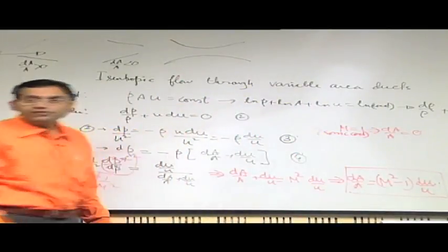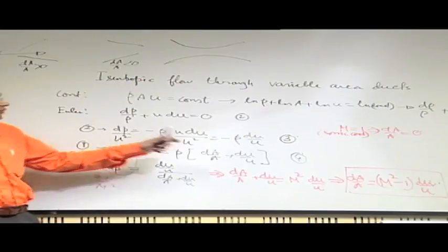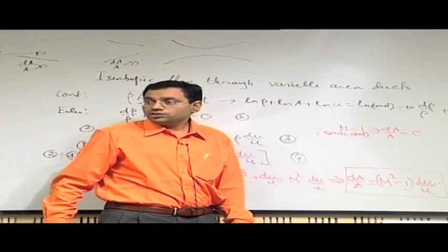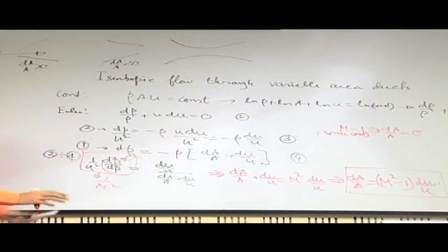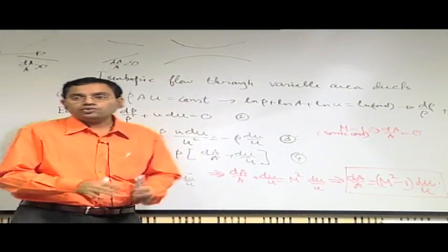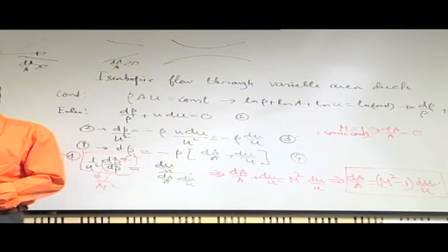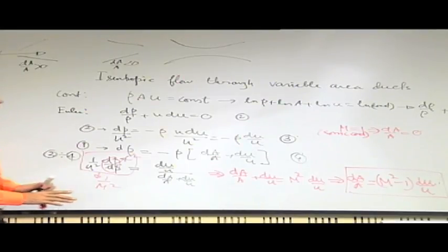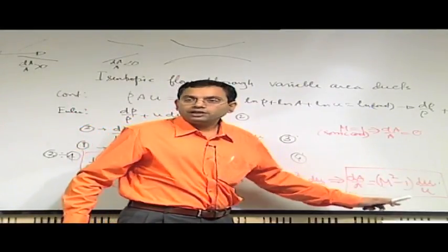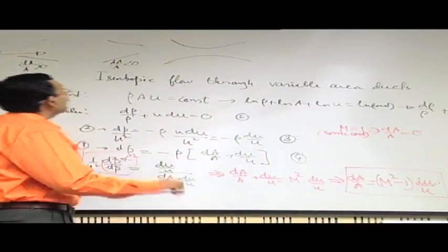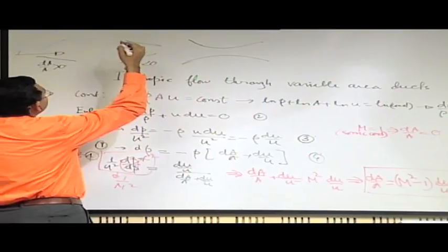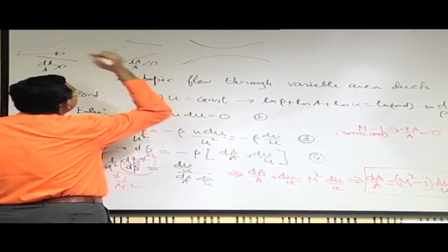In an isentropic flow it must conform to dA by A equal to 0. If you look into it mathematically, it may be either maximum area or minimum area. Physically we will see that it will conform to the minimum area. So, if you consider a possibility of these two types, say you consider this as a case,